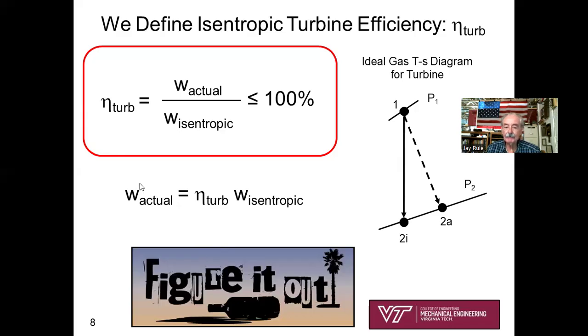Now, it is common practice to be given a turbine efficiency or to have to figure out what it is. But it's more common for me, as a practicing engineer, to be given the isentropic turbine efficiency, to find the isentropic work, w isentropic, using basic computations, and then have to back calculate W dot over m dot actual.